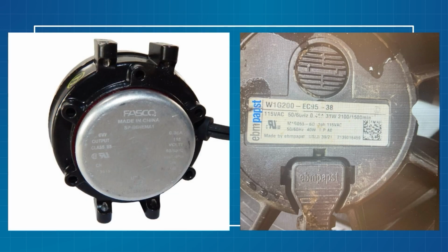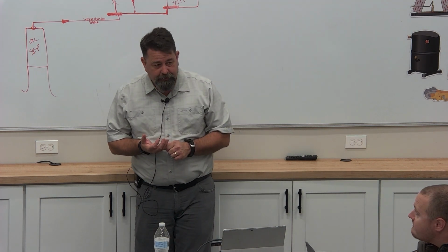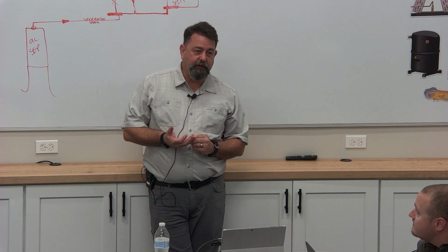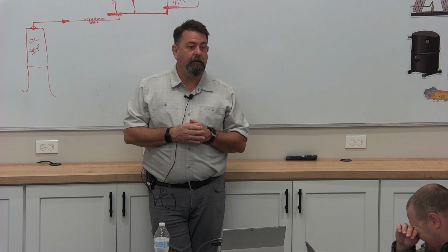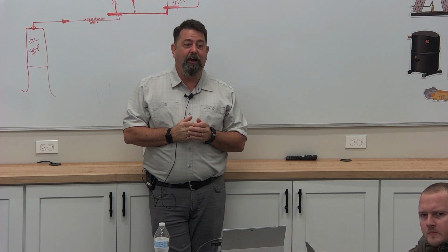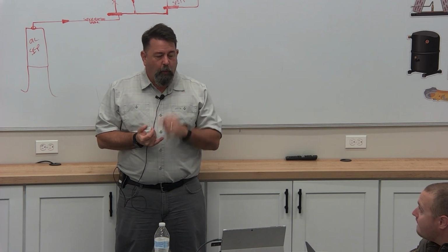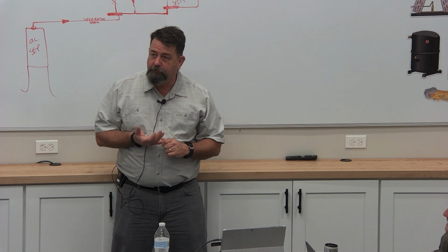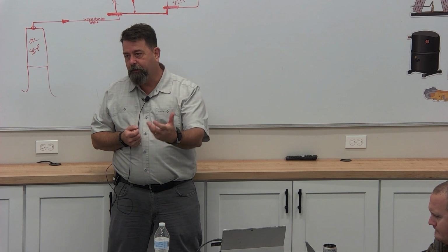All right, so let's talk about fan motors. You know, a couple pieces to this. The engineer has spec'd how much air pressure and volume he expects to go through that coil, go through those holes, bounce off those shelves perfectly to evenly balance that air current, right? When we start re-engineering this by using whatever we got on our truck, we can seriously impact that, all right? So we want to go back with exactly the same thing. There's really not a lot of room there to change the amount of air that's flowing through there.